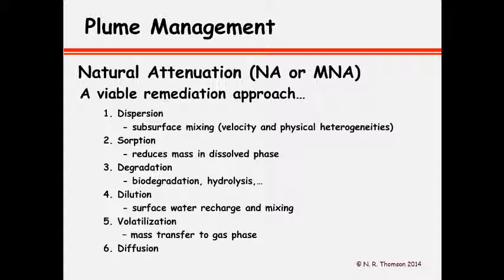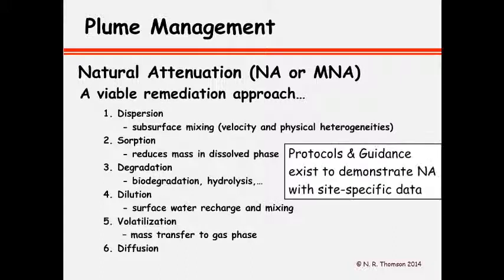to biodegradation or hydrolysis reactions, perhaps to a degree a bit of dilution from surface water recharge and mixing, volatilization from the interface between the soil air and the water table, and diffusion process. These are all processes that move towards a loss of mass within the plume.